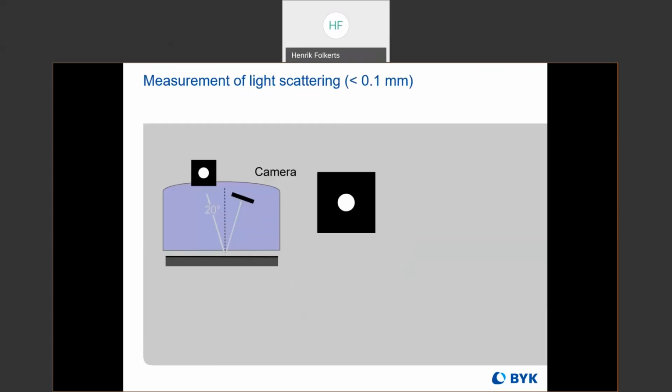And so that's why the dullness measurement was developed. If you're familiar with reflection haze, this is a similar measurement. It's how much the surface is diffusing the light as it's being reflected off. The way this measurement works is that the instrument, the WaveScan, projects a circle of light onto the surface, and it measures how much of that light is reflected back outside of that circle.